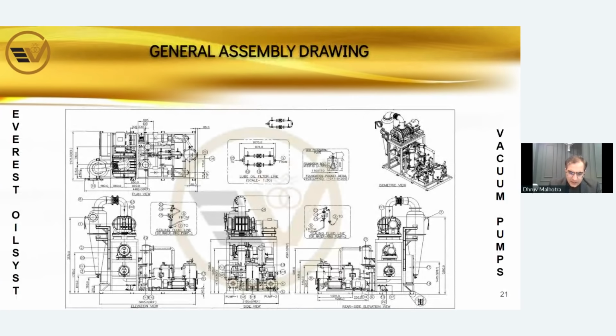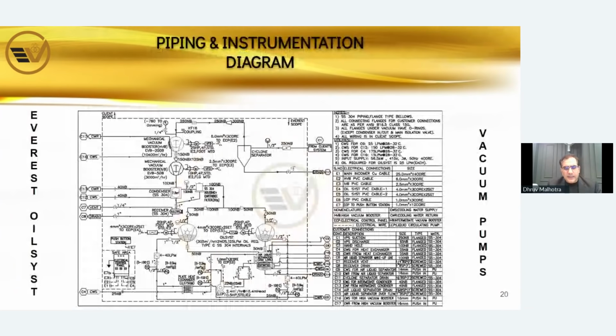I'll take a moment to highlight on the P&ID the various components used in this oil skid. If we can just go back to the P&ID. The first two stages are the two boosters. After the two boosters, there is a condenser. The flow from the condenser goes into the filter trap. That's on the side, yes. And from the filter trap, there are two liquid ring pumps at the bottom.